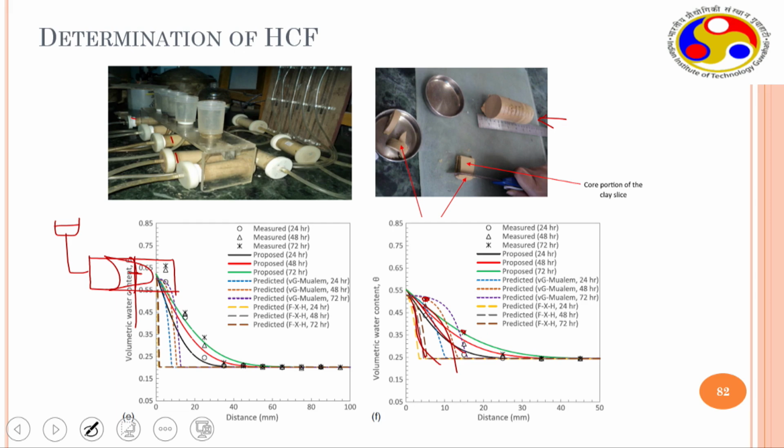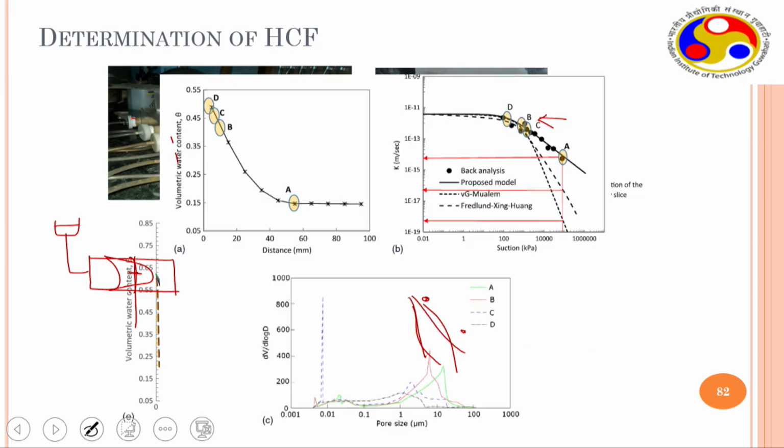Right? Richards equation is probably fine because volume change is not allowed. Here it's isochoric conditions. In the column, we don't allow the soil to expand. Okay?